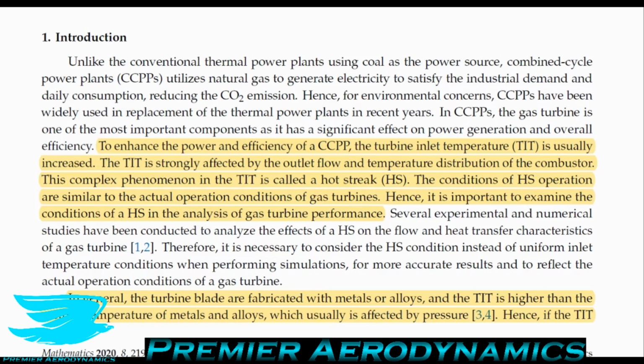Now, there are other factors you need to consider. For example, if you take out too much energy, then that can affect the upstream conditions where you're feeding flow into the turbine. But that's getting into fairly complicated issues in terms of just the turbine itself. Increasing that temperature difference is the way to increase its efficiency and its power as well.